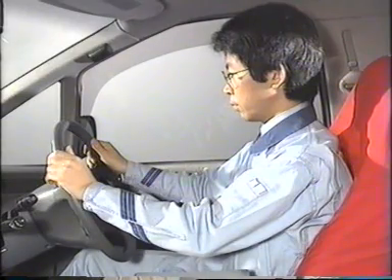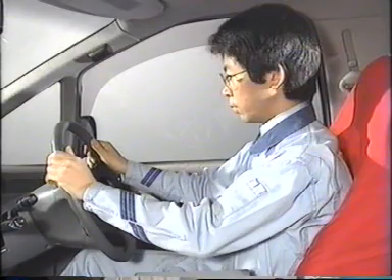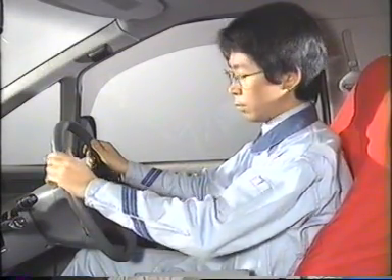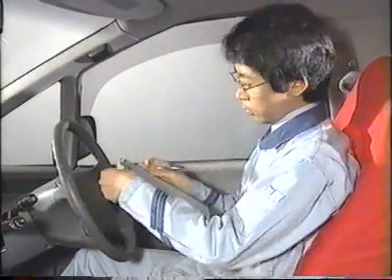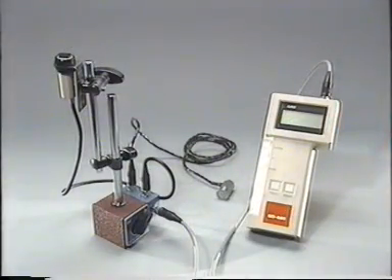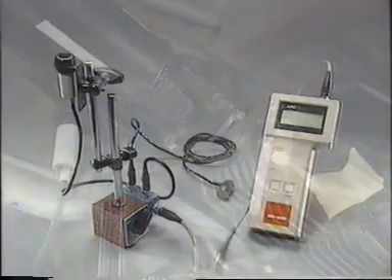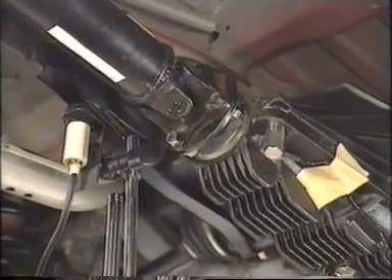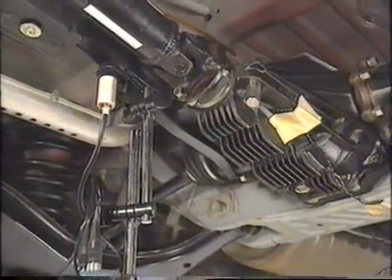The propeller shaft balance may be checked by other methods also. It can be determined by a feeling test as you move a trial weight from one point to another. Or it can be determined using a propeller shaft balancer. You will find more details about this method in the NVH Diagnosis Manual.